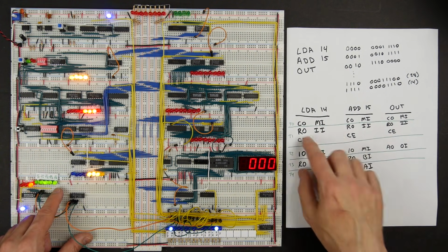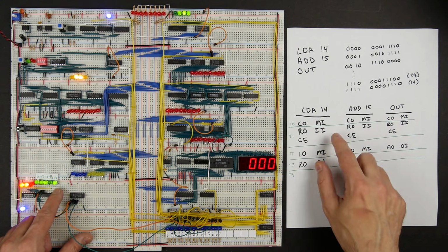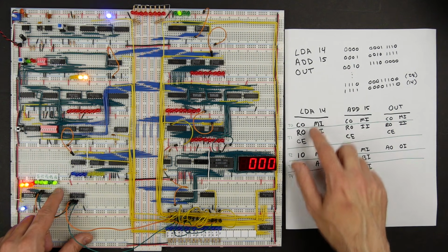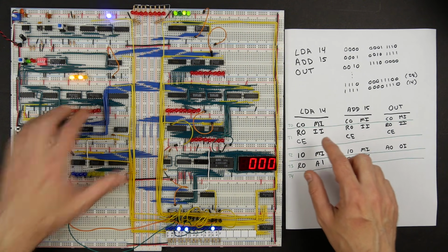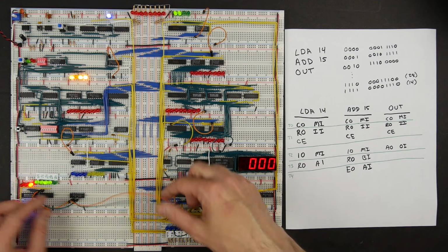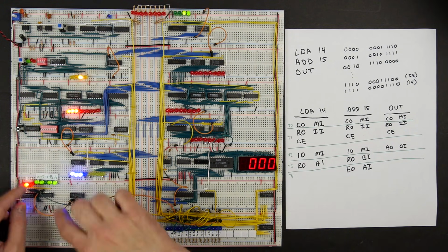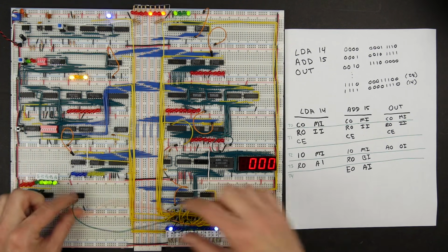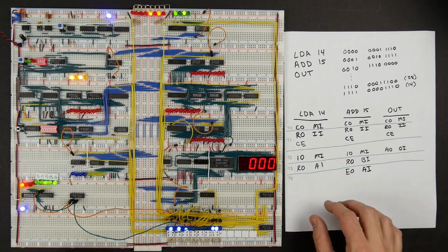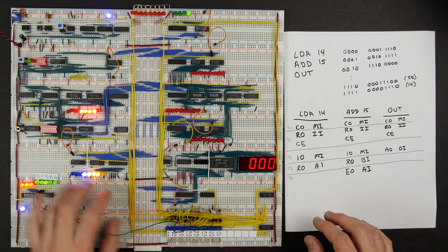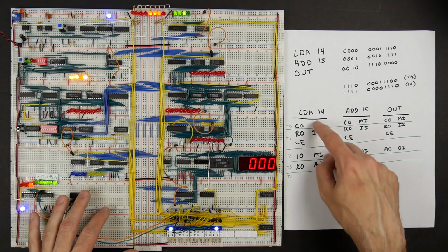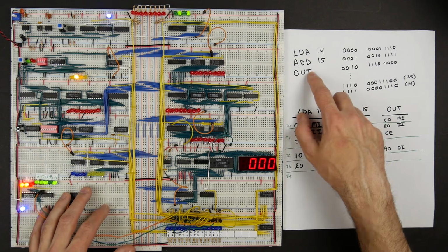And what we saw is that for T0 and T1, those first 2 steps of the microinstruction, those are always the same, regardless of which instruction we're actually trying to execute, because those 2 steps are the steps that fetch the instruction from memory and put it into the instruction register. And so in fact, we were able to temporarily wire those up just by manually connecting these signals for T0 and T1 through an inverter to the appropriate logic signals here on the control word. But what I want to do in this video is replace this temporary demonstration for those first 2 steps with logic that's going to be able to carry out all of the steps for any instruction that we might want the computer to be able to do.